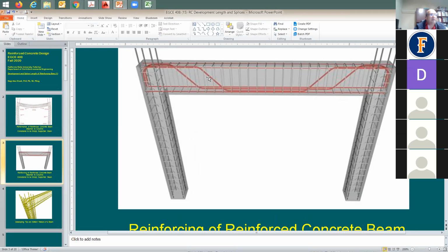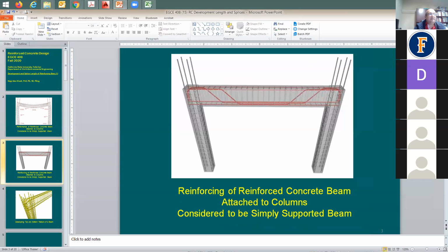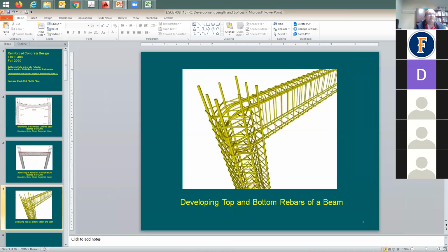It is the same. It just happened to be the same. You take the same rebar. Here's the rebar, the red one, the thick one. You bend it from here, you go up, then you come to the end of the column and hook it down. Okay, perfect, thank you. This is just to save some material. The reason they do this is to save material. Some people think this is going to be too much, and in this case, they can just do it as a separate piece of rebar.